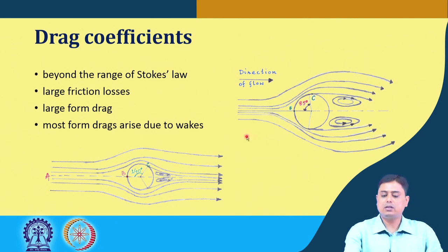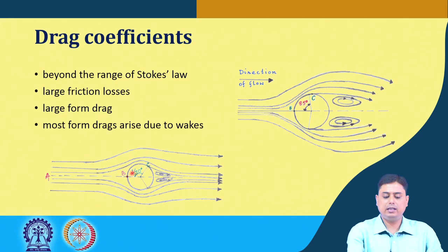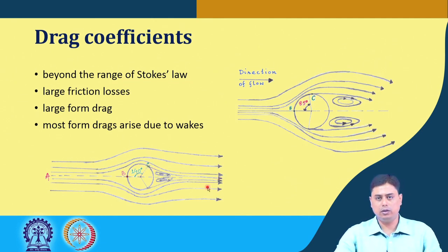So this is the case of laminar flow across a spherical object, and here this is the turbulent flow across this spherical object, and we can see that the point of separation changes in both cases. The point of separation C shifts from an 85-degree angle to a 140-degree angle, and the detachment of flow happens from this point onward, and the wake formation happens in both cases.